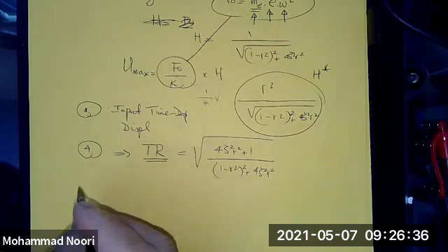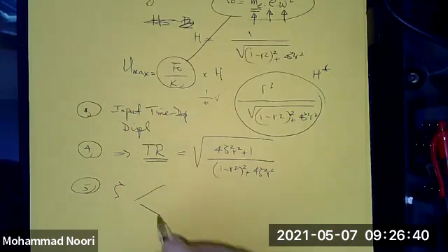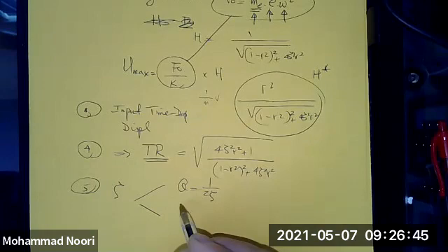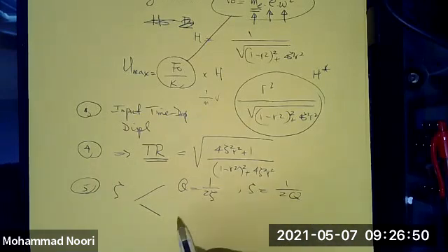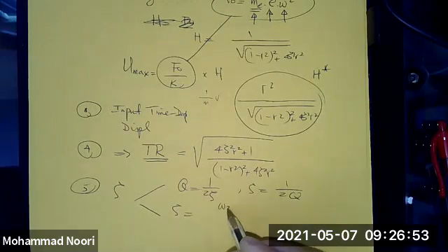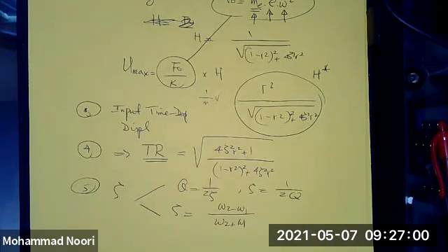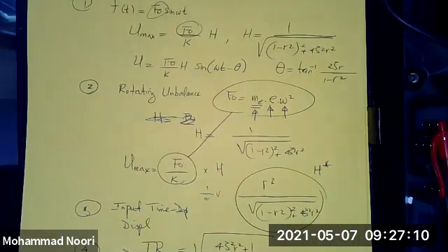So we also have now discussed evaluation of damping in two different forms: zeta is 1 over 2Q, or zeta is omega 2 minus omega 1 divided by omega 2 plus omega 1. So this is, in a nutshell, a summary of what we discussed in harmonically excited systems.